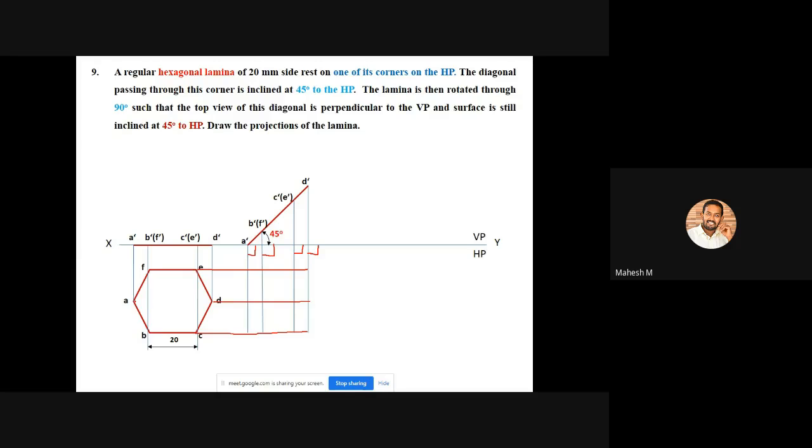Okay, so you can project like this. The first horizontal line is a projection from the point F and the projection from the point E. The second horizontal line is the projection from the point A and the projection from the point D. And the third horizontal line is the projection from the point B and the projection from the point C. Now we will get the required points for our second top view.